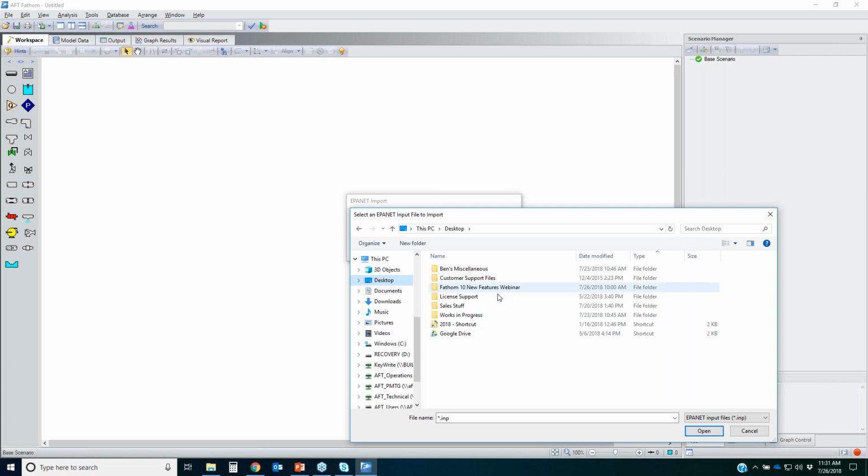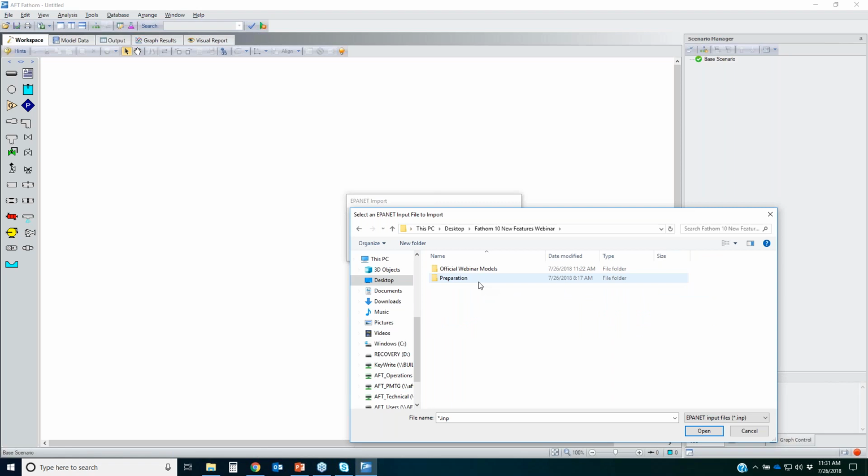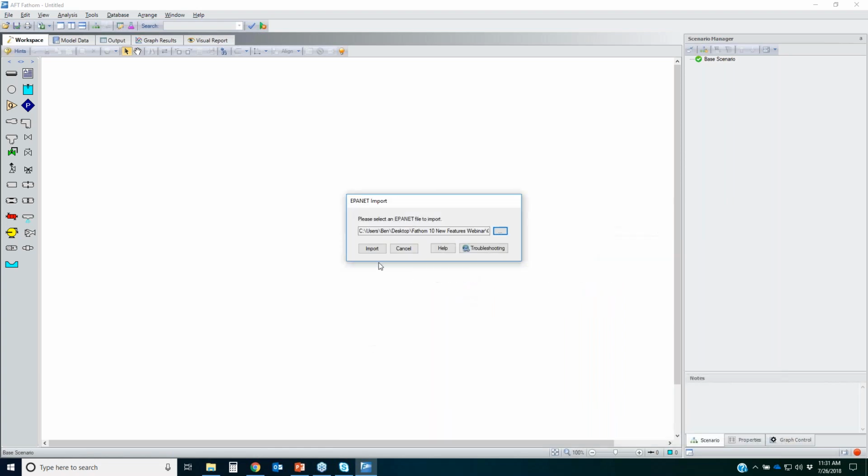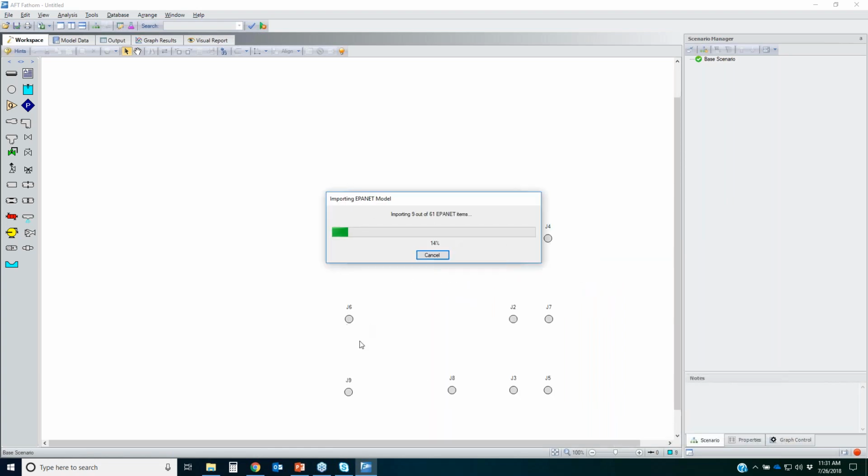The key thing about these neutral files, PCF, Caesar2, and EPANet, is that they give you flexibility to go between different software programs. So if you need to take a CAD file, you can just do it like how I've been showing you. Here's one EPANet file, and it imports that.